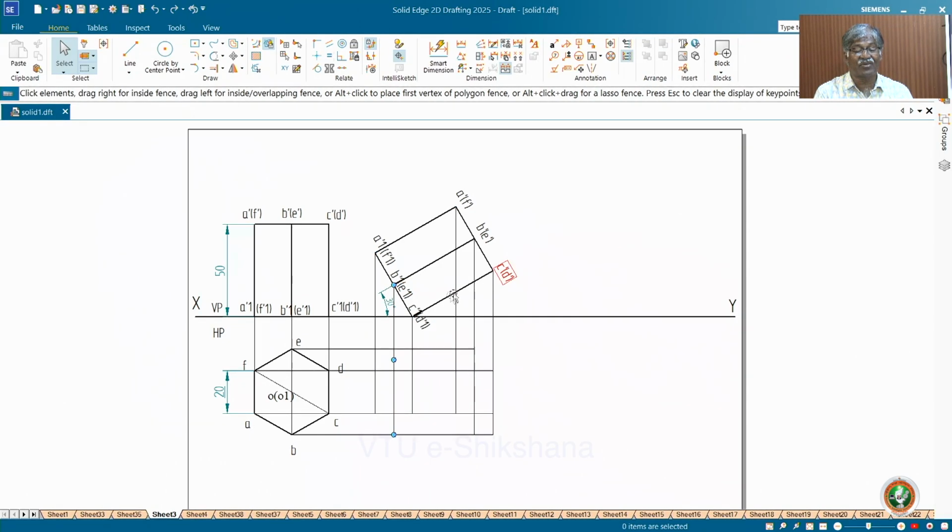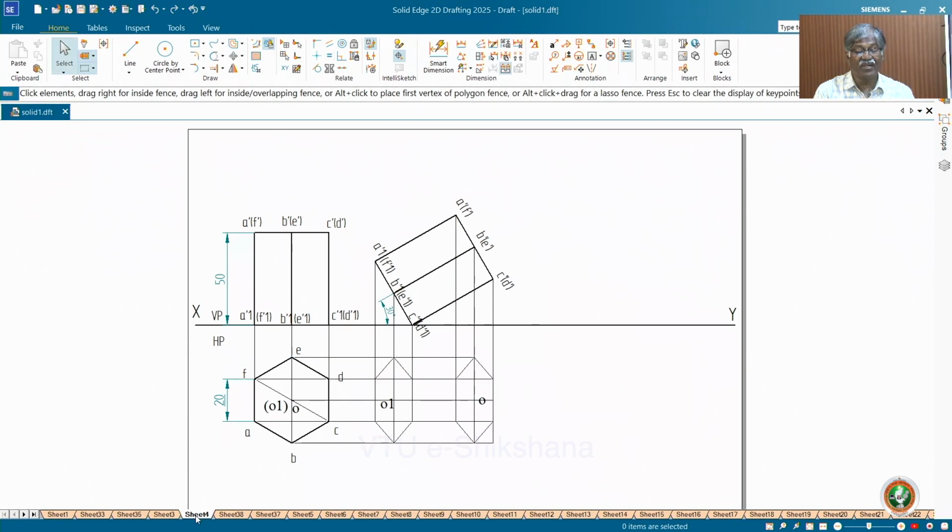So what I did, actually, I gave inclination to this. Naturally this particular line assumes 30 degree. So then you project. Unnecessary lines you can avoid by projecting only up to this, because the alignment indicator facility is there. You can do it only for the required length. Now you name it and join.